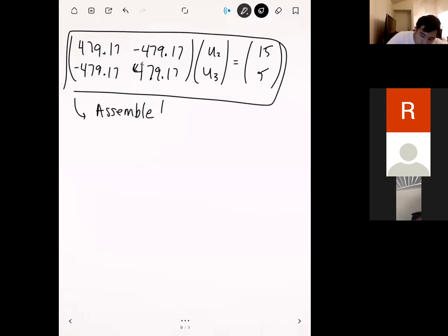All right, so now that we have the element systems for both element A and element B, the next step is going to be to assemble. We've done this before, so assembly is not anything new, and the only thing that we have to worry about now is that we have to include the element forcing contributions.